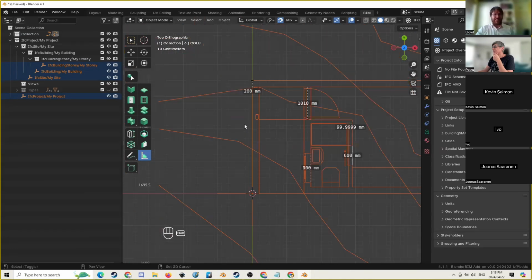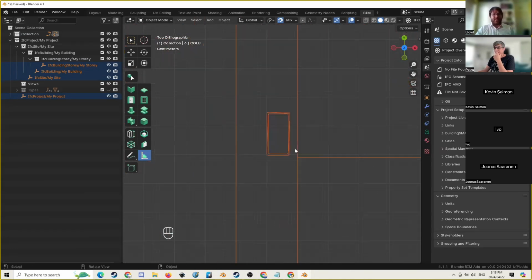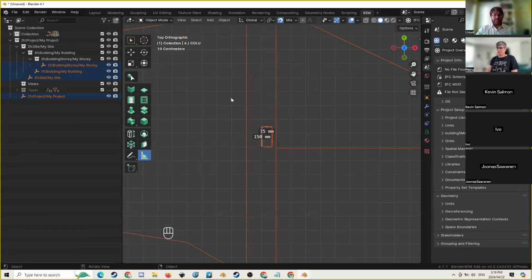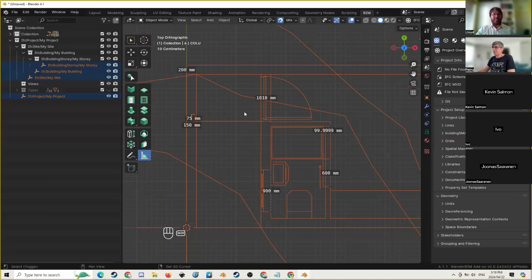And then the last thing here is a rectangular hollow section, which we're just going to measure very neatly. So I'm just going to snap there and press X. And then it's attached there. I can see it's 75. Snap here, press Y, and attach there, and it's 150. All right. So we've got our general type sizes.